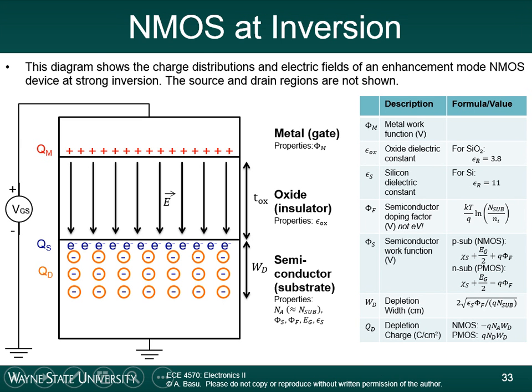So do you mean this dimension here, the depletion width? Outside, yes, it's smaller. So this depletion region width is dependent on the doping. But you're saying does it stay the same? The width altogether, I'm referring to the PN junction, because you were saying the width stays the same. But the width decreases, and it's just the side that's doped that decreases. Right? And then the other side increases.